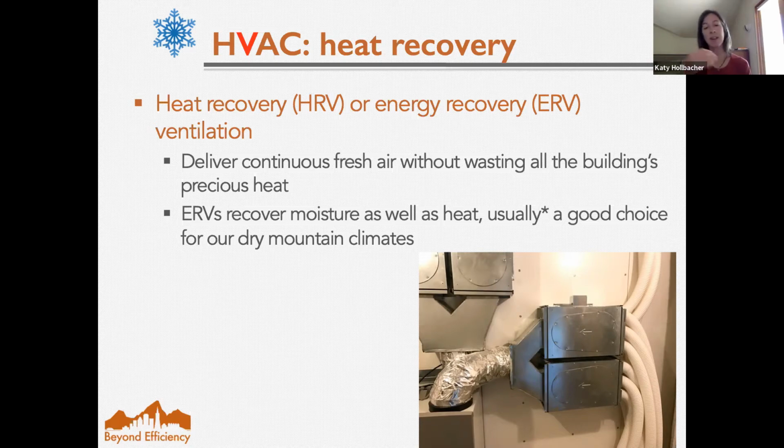Meaning if you had a 75% efficient heat recovery ventilator, you're bringing in 30-degree air, you want to get it up to 70. Instead of dumping 30-degree air into the space, it'll dump it in at 65, roughly speaking, easy math. So it helps with comfort and just hugely reduces that heating related load.